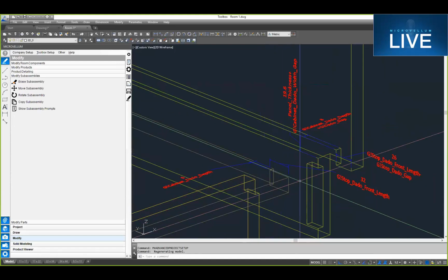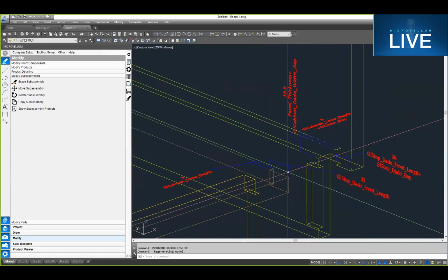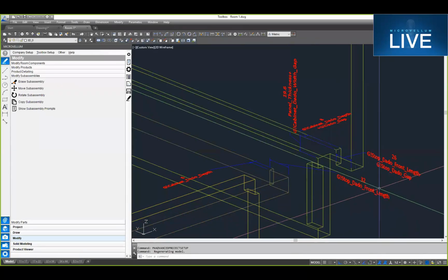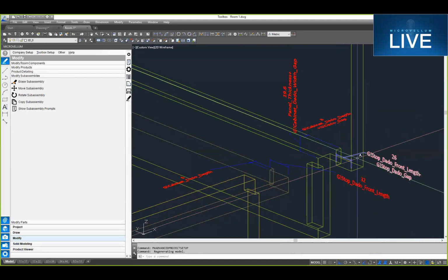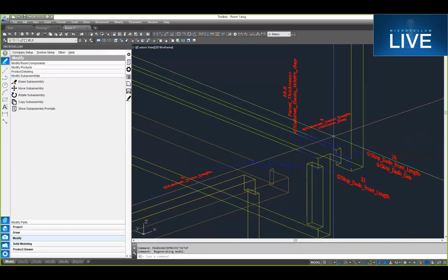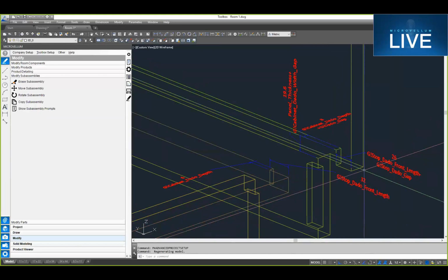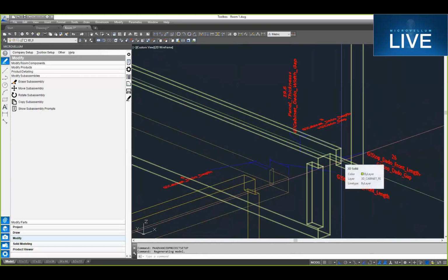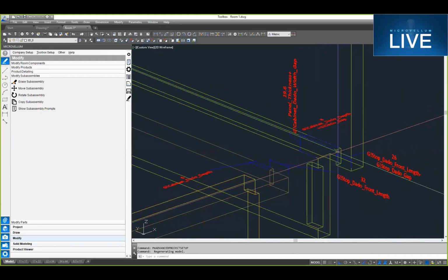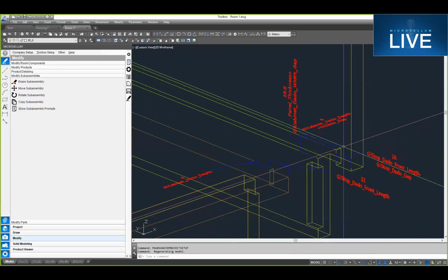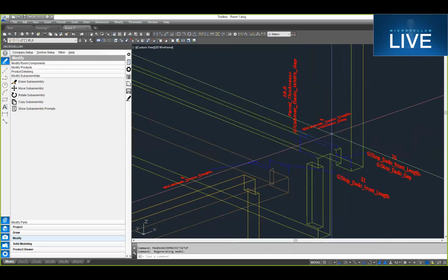So this comes into play when you're running the edge bander. You want to make sure that this dimension is large enough so that you can get your tracing wheels and your cutoff knives coming through there correctly. So you want to take that into account when you're setting up a dimension like that. And then we're going to leave a bit of a gap there to account for the radius, and so that's our stop dado gap. And so that's going to be the gap when those two parts come together. You're not going to see it. It's going to be a void inside of that groove that you'll never see. And there will be a little bit of a radius on those parts depending on how you machine them. And so that's going to take that into account.